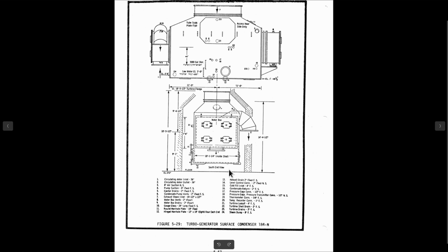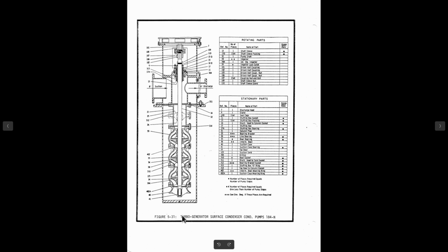This is kind of a physical drawing of it. This would be on the back wall looking towards the Foster Wheeler boiler. That's the inlet line, return line, water box doors. Condensate pumps would sit over here. This is the surface condenser pump. 3-stage turbine well style pump. Suction from the hot well, dropping around the outside. It's picked up down here is your suction.